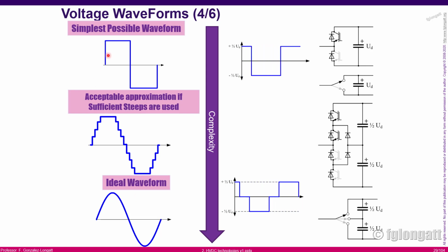the first and the most simple approximation in order to create a sine wave. And that is the square signal that we are generating using two switches over there, okay? As you can see, the next approximation is using more switches. If you go back here to the right-hand side, you can see that right now we are using 4 switches.